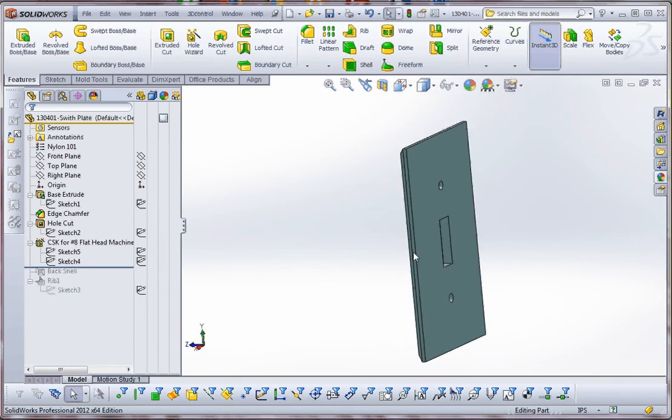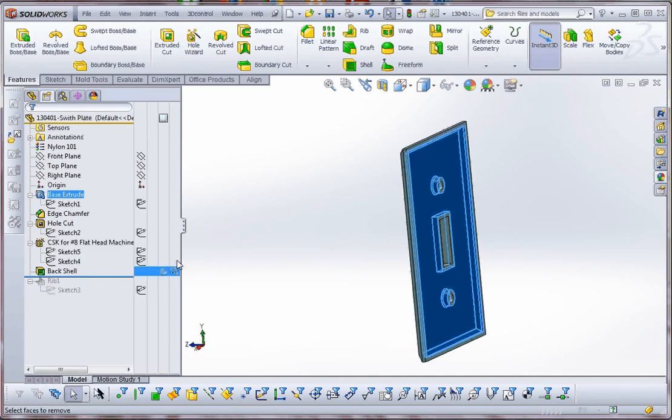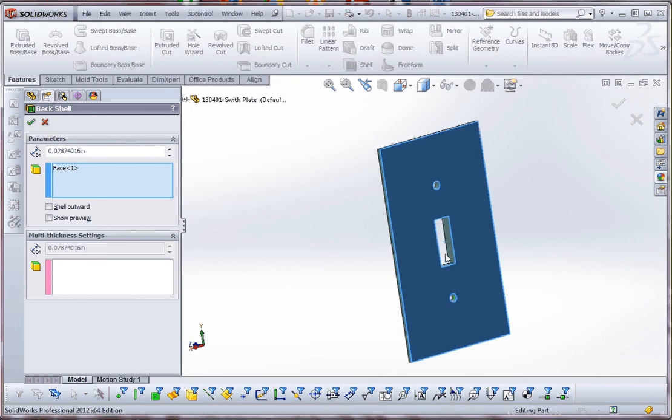If we look at the back here, it's just a flat plate back here, particularly to hollow it out to provide less material when you're actually putting your part together, and it makes for a much better design. When you're doing plastic extruded parts, you want a very consistent wall thickness. The parts will probably come out with a lot more integrity and a lot fewer gaps and warpage that might come from that. So typically what you do is you shell it out, and we have another feature in here which allows us to do that. So here's a shell feature, and what we did is we chose a face, just this back face back here, and it avoids some of these cuts in here, and it puts a thickness in here all the way around.